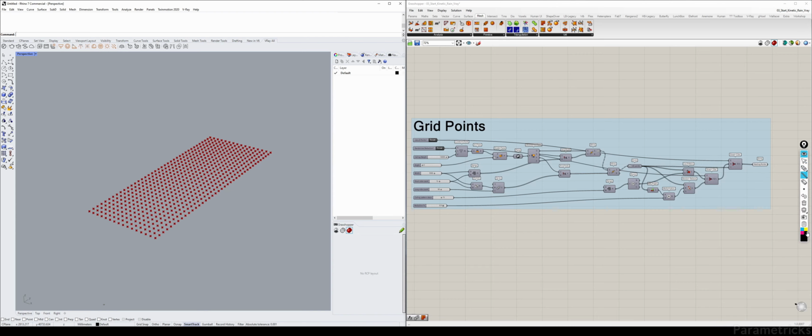first off, what we'll try to do is from the short side, we will make a line that is slightly larger than the total width because we want to make sure that Grasshopper will intersect to the surface, and we don't want to leave it to chance where it might intersect on the side and then things could fail. So we're going to make it a little bit bigger. And then from that point on, we will introduce a set of points.